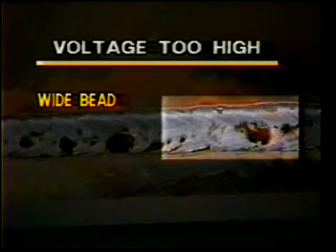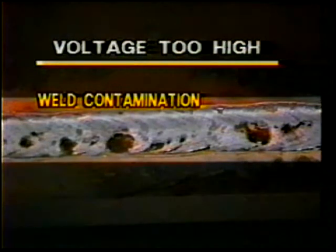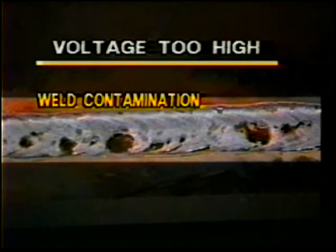Increases, resulting in lower penetration. A longer arc length increases the chances of the weld droplet, as it is traveling across the arc gap, picking up contaminants from the atmosphere.